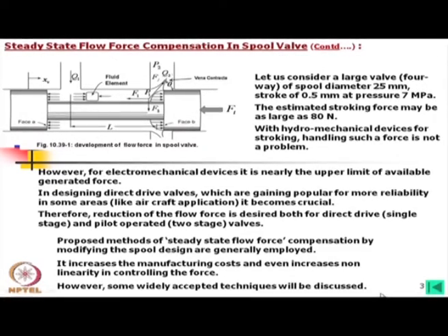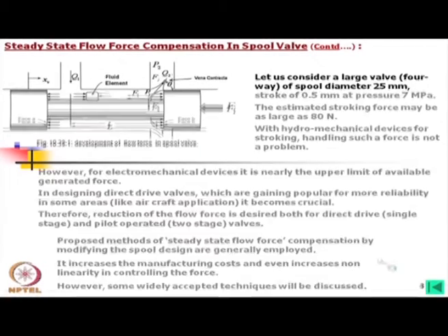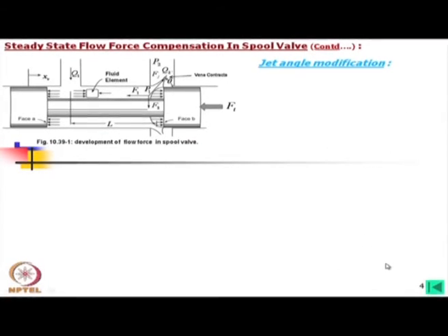Now, one can think of many methods, but all may not be acceptable due to the nonlinearity in control or too much increase in the cost of manufacturing, but there are some popular designs which are accepted for flow force compensation. Now, one is jet angle modification.